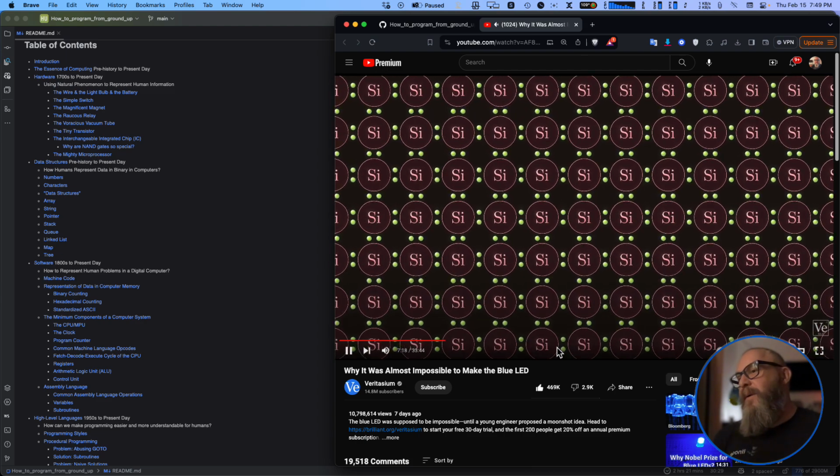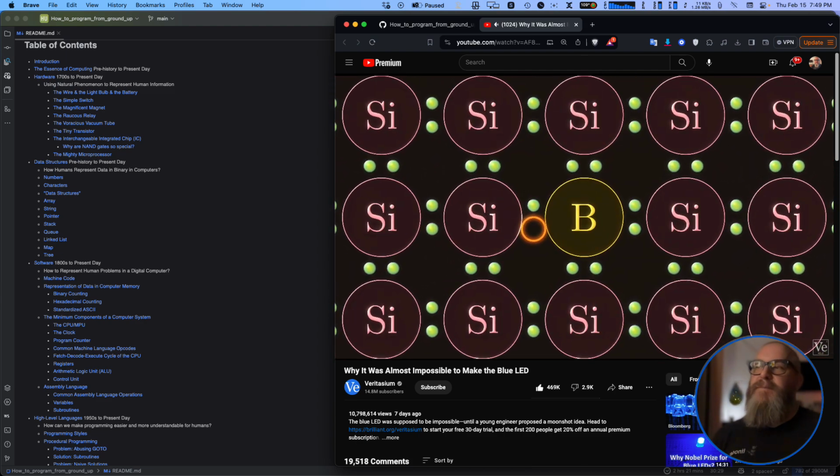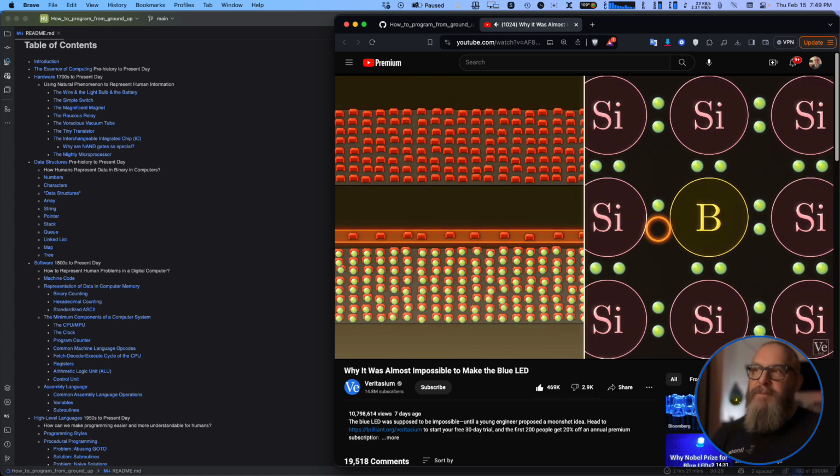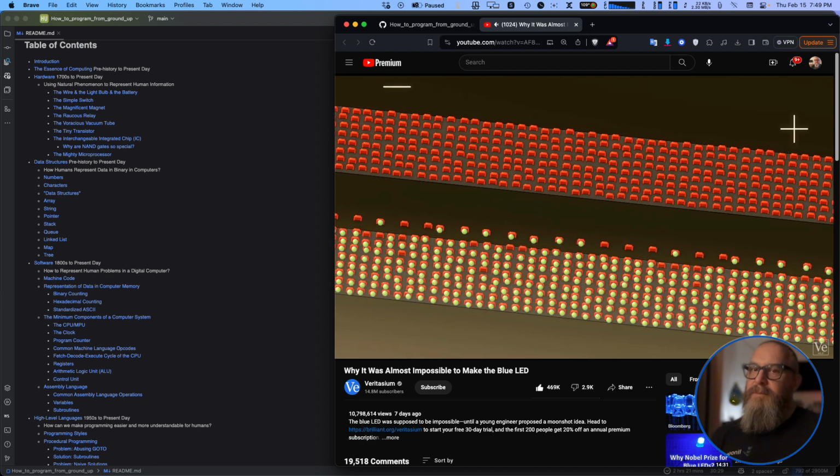Silicon, you add a small number of atoms of, say, boron. Boron fits into the lattice, but brings with it one fewer valence electron than silicon. So it creates an empty acceptor level just above the valence band. And with a bit of thermal energy, electrons can jump out of the valence band, leaving behind holes. It is these positive holes which are mostly responsible for carrying current in the P-type semiconductor. Again, the material overall is uncharged, it's just that most of the mobile charge carriers are positive holes.